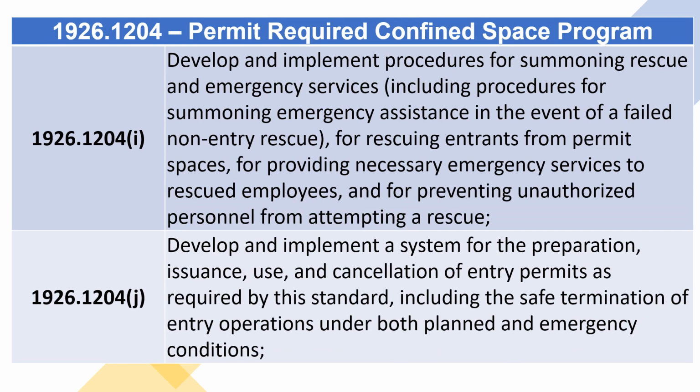1926.1204(i). Develop and implement procedures for summoning rescue and emergency services, including procedures for summoning emergency assistance in the event of a failed non-entry rescue, for rescuing entrants from permit spaces, for providing necessary emergency services to rescued employees, and for preventing unauthorized personnel from attempting a rescue.